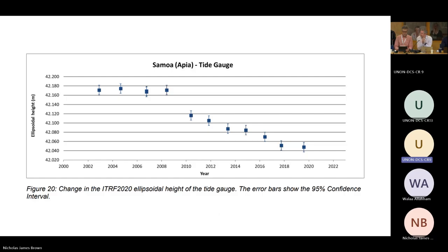Yeah. And also, I think when you go offshore, the requirements for positioning and danger to navigation are more relaxed. The IHO measures they put for surveys offshore are more relaxed as compared to when you're getting through the ports. And different countries like the US get their mean waters every year because they have the resources to do it. Other countries use the lowest astronomical tide, which takes around 28 years to get a concrete model. But if your country is able, they use the yearly tidal datums if they want to.